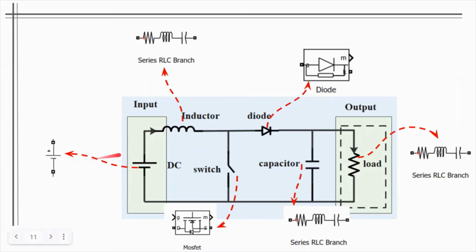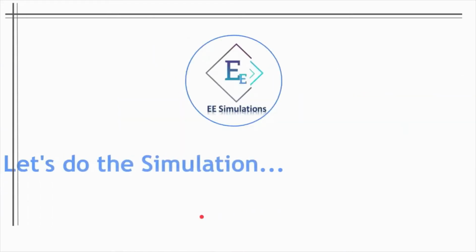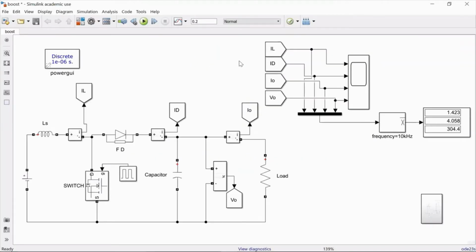So what components will we require during the simulation? Of course the DC supply, then the RLC branch, in which we will choose the inductor, this is the diode, this is the load, and this is the capacitor, this is the switch. We are using a MOSFET as the switch. So let's move toward the simulation. I have already placed all the components here.